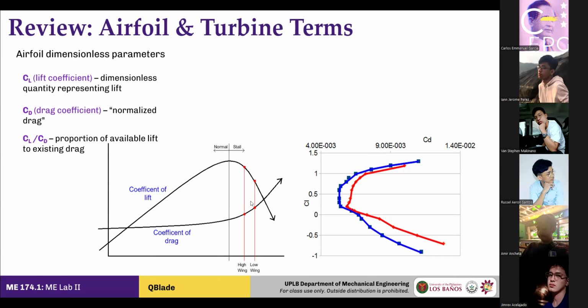So, when you're examining yung characteristics ng aircraft, it's important to note yung point of stall and yung point of alpha zero. So, pag symmetric yung airfoil mo, as in NACA terms, you have zero camber. So, your airfoil is 00XX. Yung lift mo at angle of attack 0 would also be, well, 0. Pero, if you introduce that camber, that asymmetry, kahit na ang angle of attack mo ay 0, positive pa rin yung coefficient mo of lift. Yan nga lang, malakas pa rin yung drag mo.